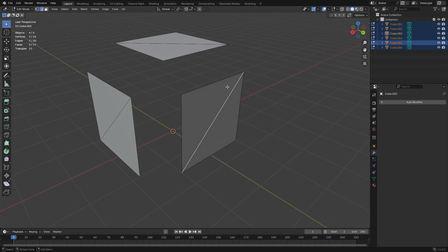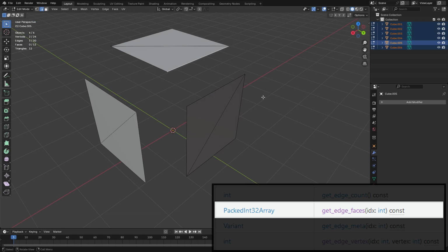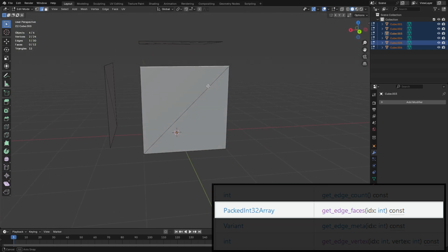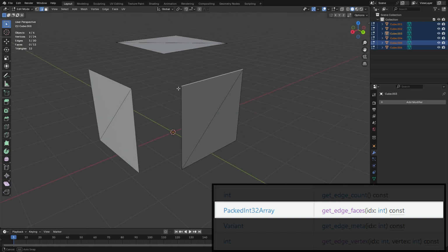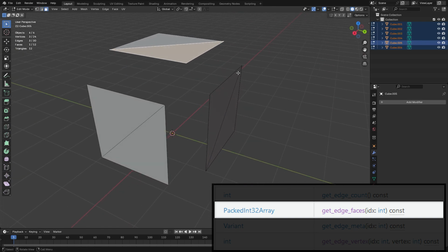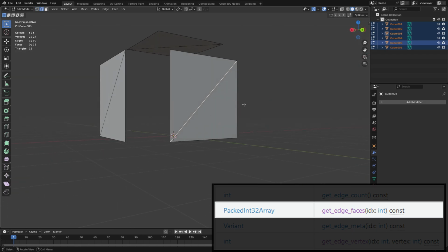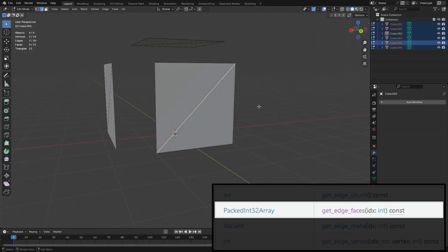And what kills the Mesh Data Tool approach is that its edges don't know about the faces they have. Looking at this method, it's logical to assume that an edge lying between 2 faces will return you 2 face indices. However, what happens in reality is this edge returns you 1 face and its copy on the other side returns you the second part. And those edges aren't tied by any data at all. They have different indices, different vertices, etc. The only edges that know 2 faces are diagonal triangulation edges because they don't have a sharp angle.